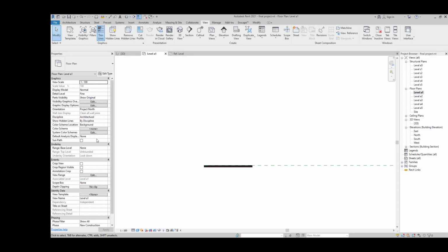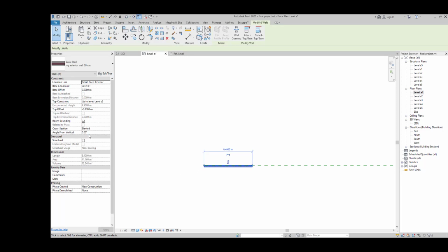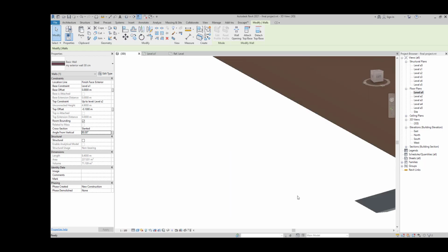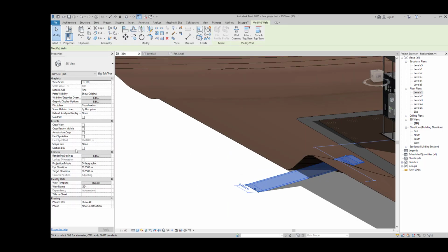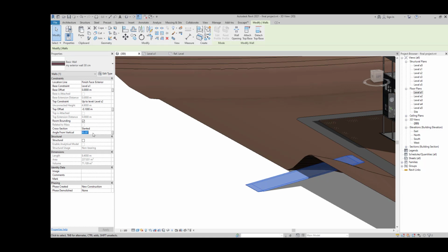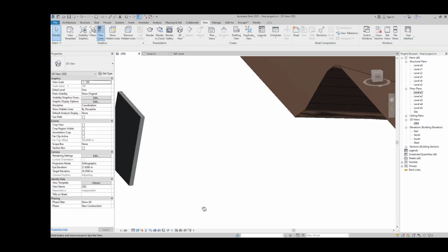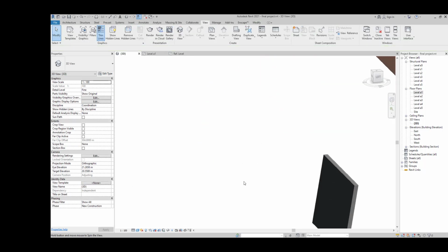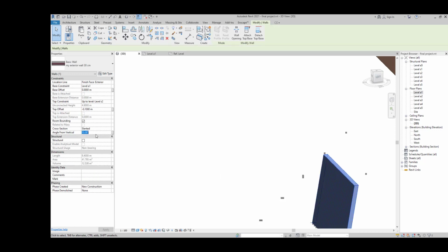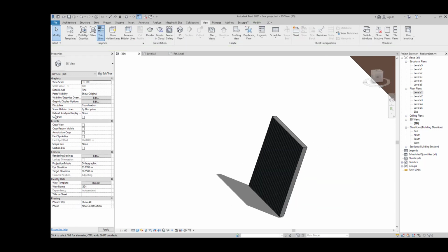We are going to check it out, and after that, once you turn on slanted, the angle will be on, so you need to choose one angle. 90-degree, for example, is our original angle. I'm gonna choose, for example, 80-degree. So we are going to have this one right now, and we need to change it to 10-degree maybe. Yes. So we are going to have a slanted wall with a specific angle. It's a very useful and easygoing method.